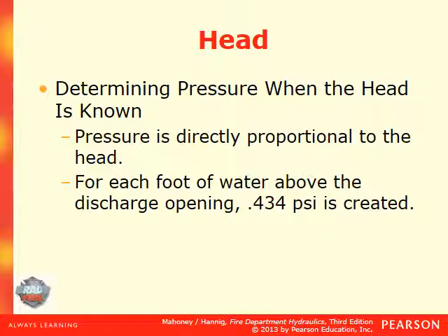So let's dive into another math problem. Determining pressure when the head is known. The pressure is directly proportional to the head. So for each foot of water above the discharge opening, 0.434 psi is created. Or in fire service, basically we use 0.5 for round numbers.